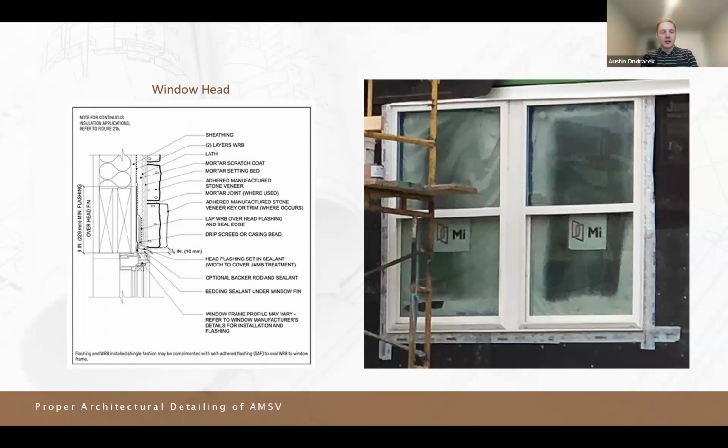Looking at window head, again, very similar to what we've showcased, talking about proper flashing, all those different things, bedding sealant under the window fin. There are a lot of variances that can come in how the project is going to be finished when installed, making sure that the stone is not an afterthought for the project and something else causes an issue later down the line. Just great to be aware of on the front end.